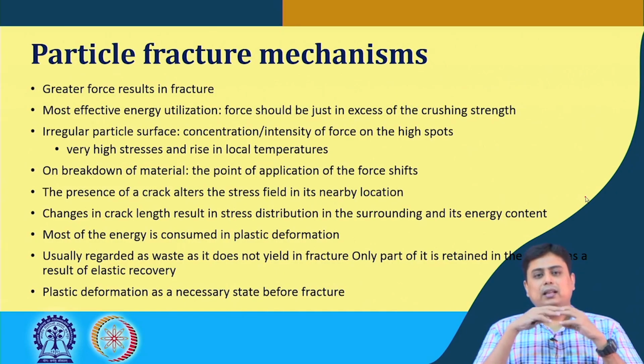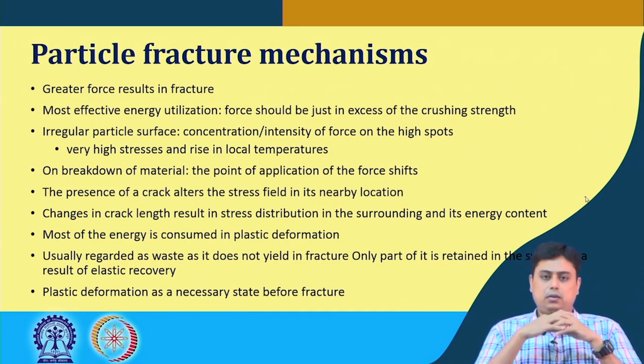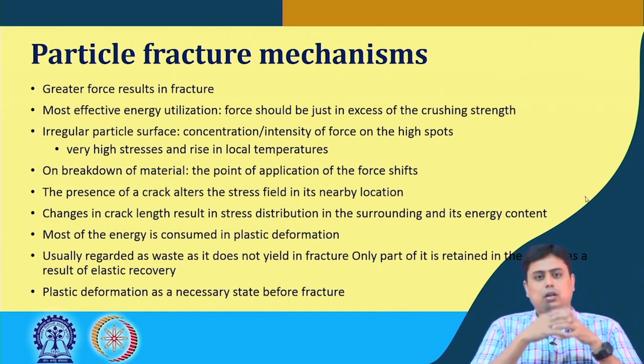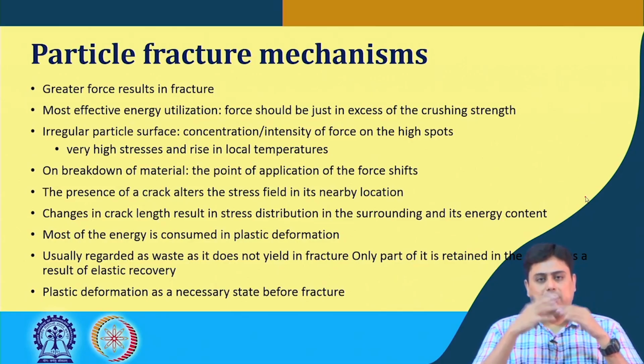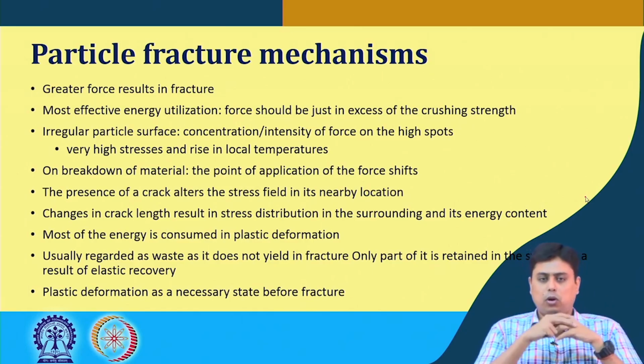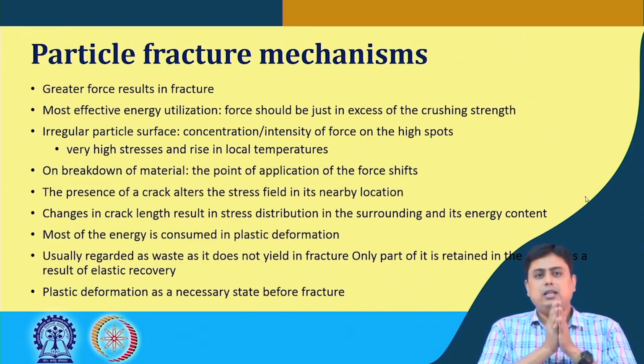Now, the particle surface is irregular in nature. There are hardly any smooth surfaces; ideally, that is not there. So, this irregular particle surface has some high and low spots. That means the applied load or force actually hits the high spots, so there is a concentration, or intensity, of the forces on these high spots.